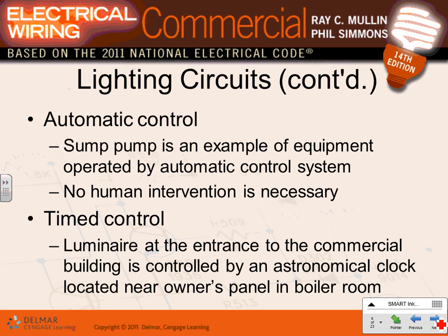Because of auto control. When they did auto, again, this is not light, but they have a sump pump. Obviously, you don't want to turn the sump pump on and off. There's a floating switch that controls the sump pump. That's their auto control. Auto means Brian doesn't have to push the button. If the water goes higher than a certain level, the floating switch triggers a little contact, closes the contact, and the pump starts pumping water. When it goes below a lower level, it stops, right? You've seen the sump pumps, how it works.